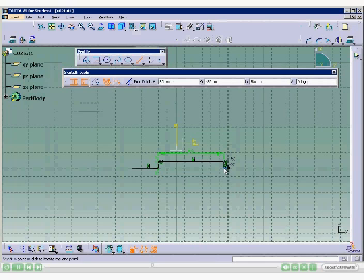Select the end point of the second vertical line as the start point of the third horizontal line, and move the cursor horizontally toward the right. Click to draw the line when the length in the Edit box shows a value of 45 mm, or enter the value manually in the Edit box. Select the end point of the previous line as the start point of the third vertical line, and move the cursor vertically upward. Click when the length of the line is 50 mm.